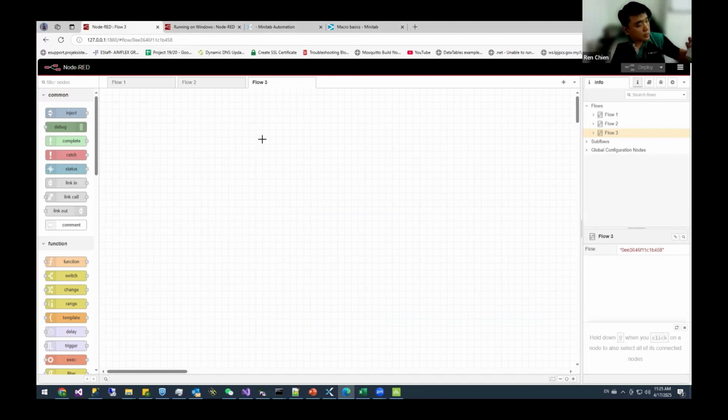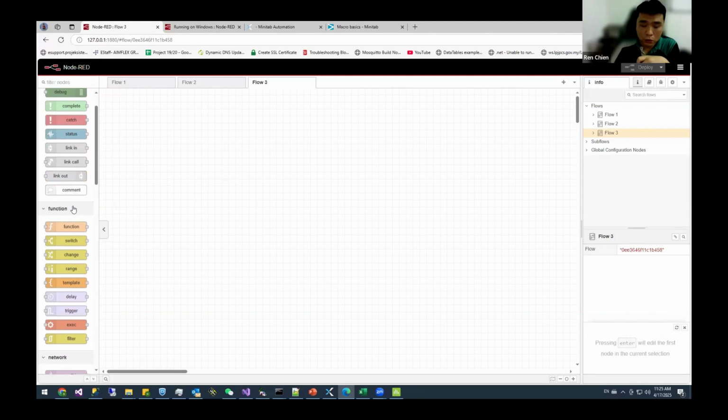An IoT box like this one, the ISM 4001, comes with Node-RED already inside. You only need to key in the IP address and the port number so you can access the IoT platform inside the box. So what can this IoT platform help us to do? It can help you set up a scheduler to pull the data from the machine.